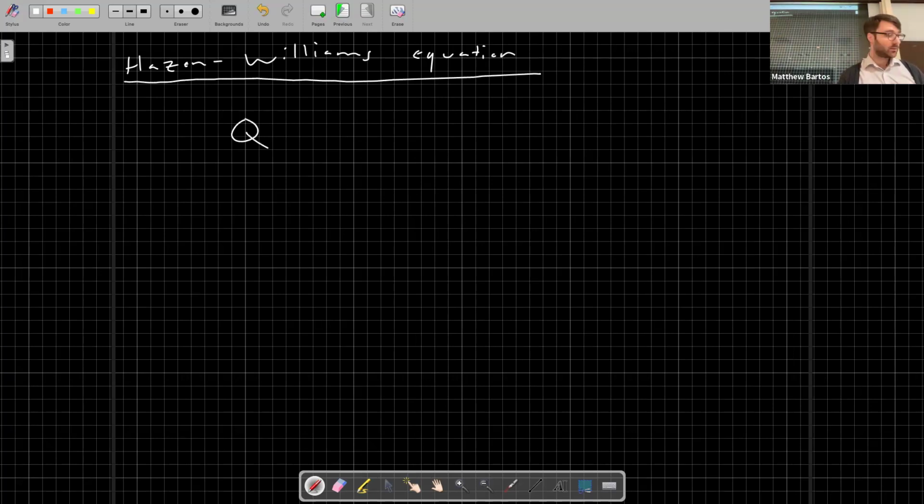The discharge Q is equal to our unit coefficient phi HW times our roughness coefficient CHW times the cross-sectional area times the hydraulic radius to the 0.63 power times the friction slope to the 0.54 power.